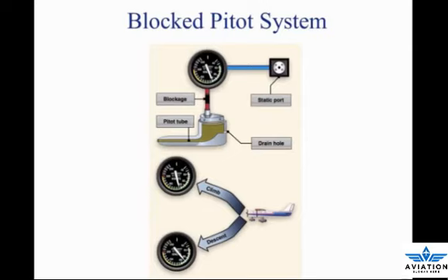Because airspeed indications rely upon both static and dynamic pressure together, the blockage of either of these systems affects the ASI reading. Remember that the ASI has a diaphragm in which dynamic air pressure is entered. Behind this diaphragm is a reference pressure called static pressure that comes from the static ports. The diaphragm pressurizes against this static pressure and as a result changes the airspeed indication via levers and indicators as seen above.